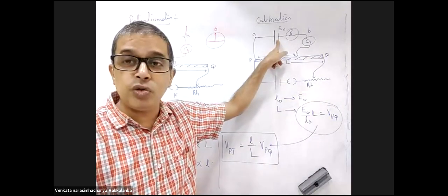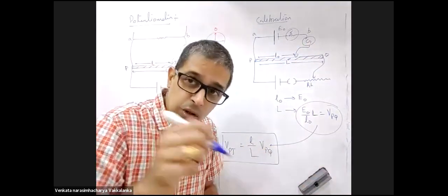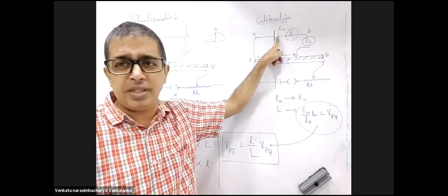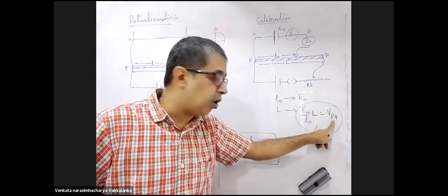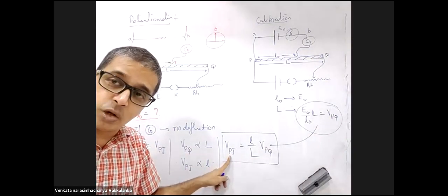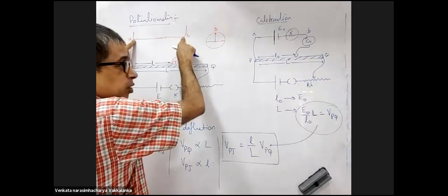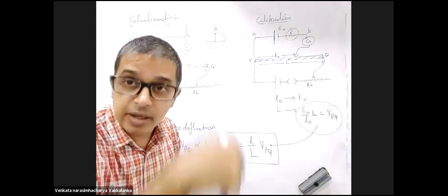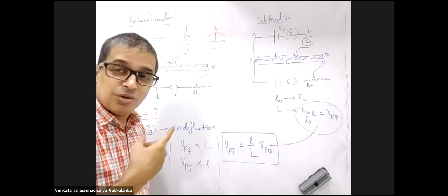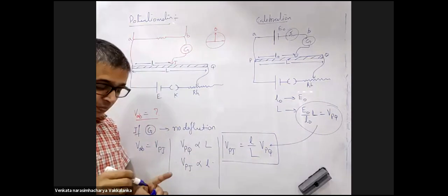L0 corresponds to E0. How? Because the galvanometer showed null deflection. You found out that length for which there is null deflection. So L0 corresponds to E0, unitary method. Total L will correspond to how much of a potential difference I know now. Substitute here, will I get the potential difference across PQ? If you get the potential difference across PQ, you got it without taking any current from the circuit. So it's an ideal voltmeter. Yes or no? Yes, sir.